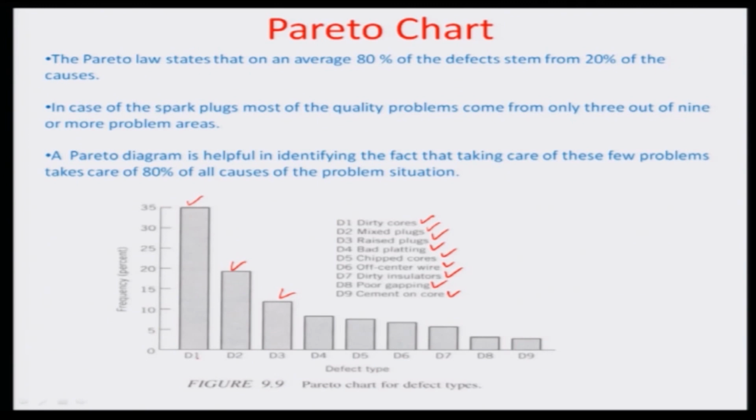So you are basically recording defect wise frequency of occurrence as a percentage out of 100, and then the idea is that once you have recorded this, you can identify what are the first 3 defects of topmost priority which has to be focused in order to solve the quality problem. Okay, so it gives you a sort of prioritization as to what has to be focused first to eliminate, so that the overall level can come down to a reasonable level, and then if you want a 0 defect you can go to the lower ones later on.